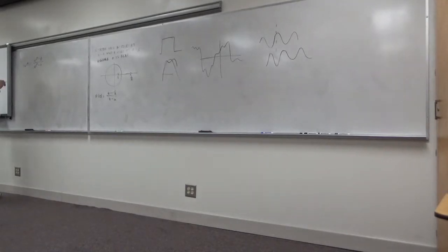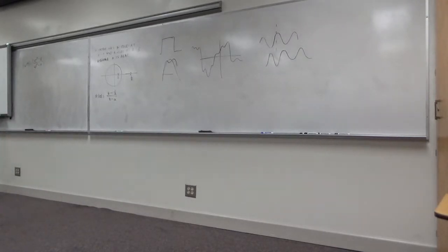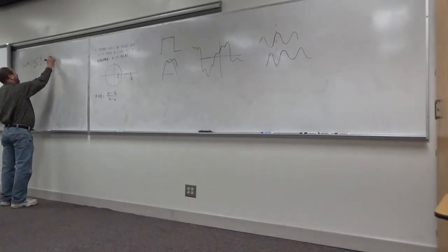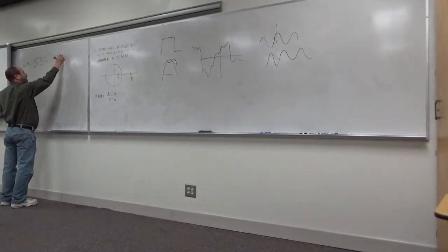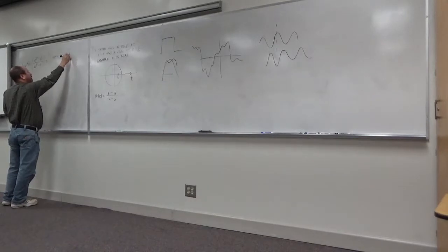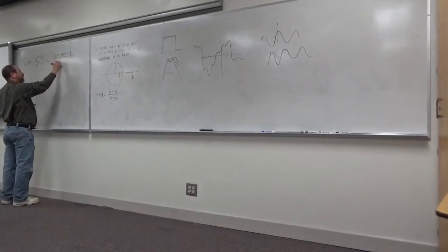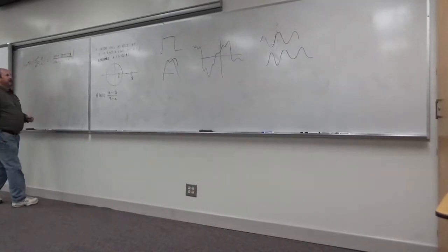We've been talking about gain primarily, so I'm going to take the absolute value, the magnitude, because it's a complex expression. Okay, on the right-hand side, e to the j omega can be written as cosine omega plus j sine omega minus 1 over a. And in the denominator, that is cosine omega plus j sine omega minus a. And then I want to take the magnitude of that.